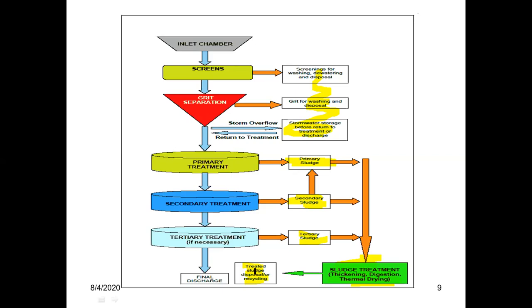They take the wastewater sludge to their cement kiln, and in the cement kiln, the sludge is disposed at higher temperatures, because the temperature inside the cement kiln is very high. It is more than 1000 Celsius. So at high temperature, those heavy metal containing sludges are disposed and incinerated.